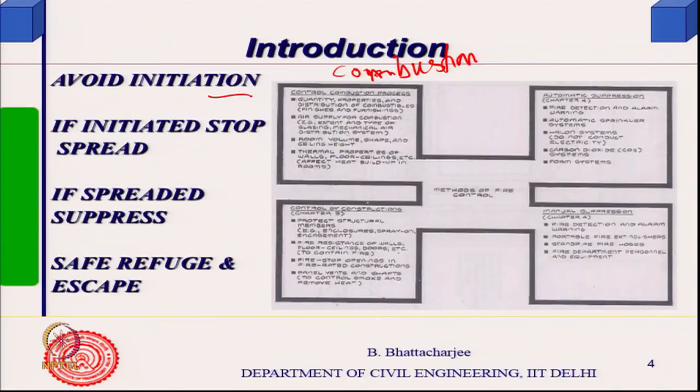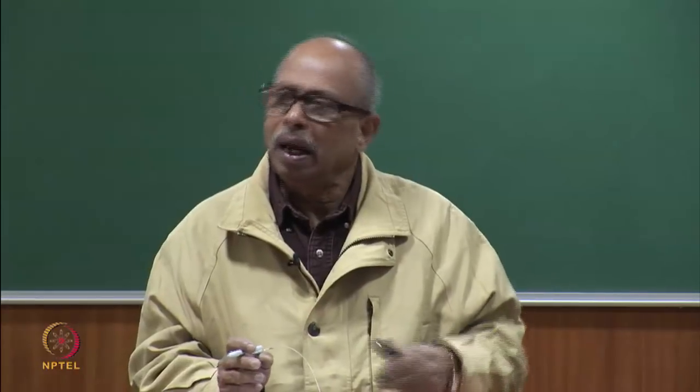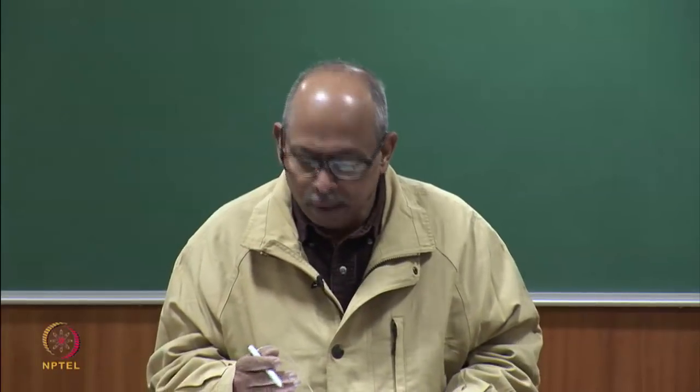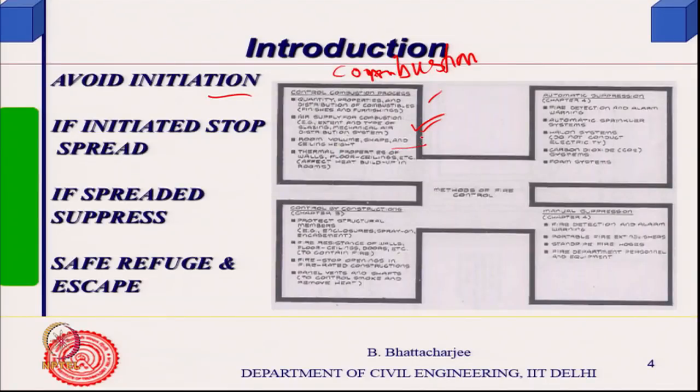So, this depends upon what we will go into in detail, but just as an outline: quantity of the combustible material within the space, right. Then air supply, because as you shall see in the next slide, three things are essentially required for fire. One is the fuel, the other is air, and for it to initiate you need heat. After that it sustains on its own. So, air supply comes from ventilation into the building, and the combustible material present provides the fuel, and then it also depends upon the space, the volume of the room, etc.